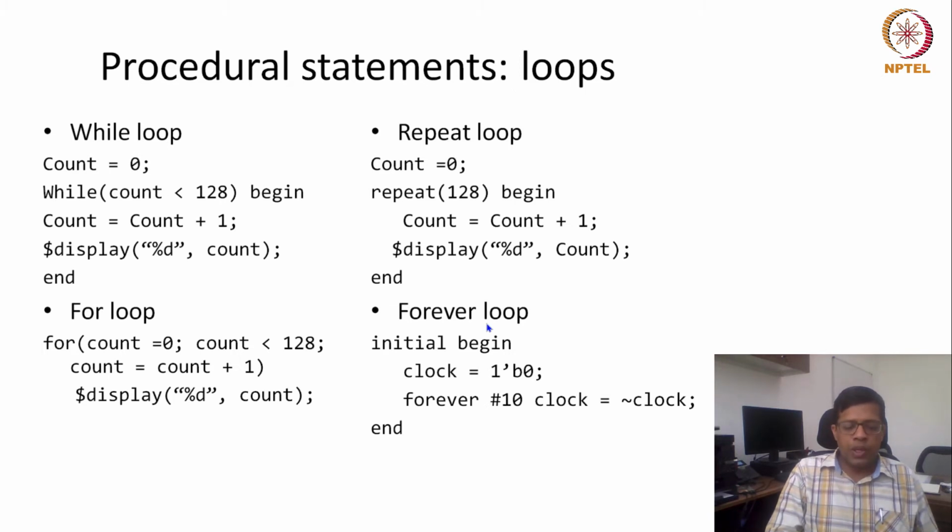For example, let's say you're doing sorting. Whenever the sort finishes, you can generate a signal, and when the signal is 1, then I will do a $finish, or I'll finish my simulation. Here, for simplicity, because we don't know how many cycles it will take, we are writing forever, but in some other block we are writing a $finish according to when my simulation should finish.